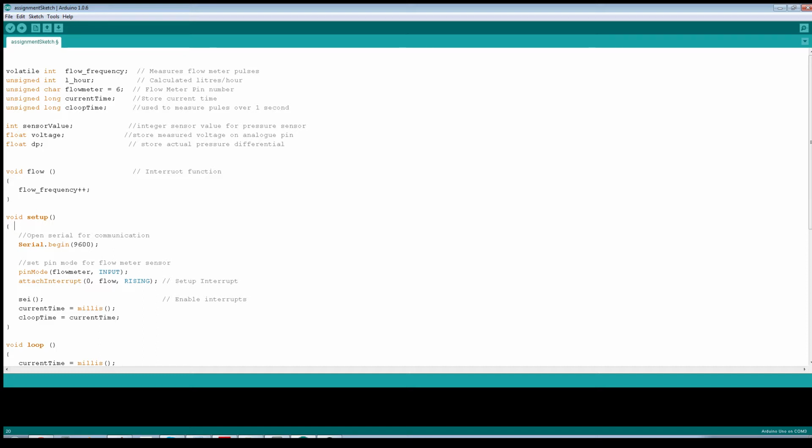Basically, to do that we've got to measure two performance aspects of a pump, and that's the flow rate, so how much fluid is actually moving through the system, and how much pressure loss is over the system. The pressure loss over a system is a measurement of the system head, so that's the sum of all the restrictions. How these two values interact is that the higher the system head, so the higher the pressure loss over a system, the harder it is to move fluid through it.